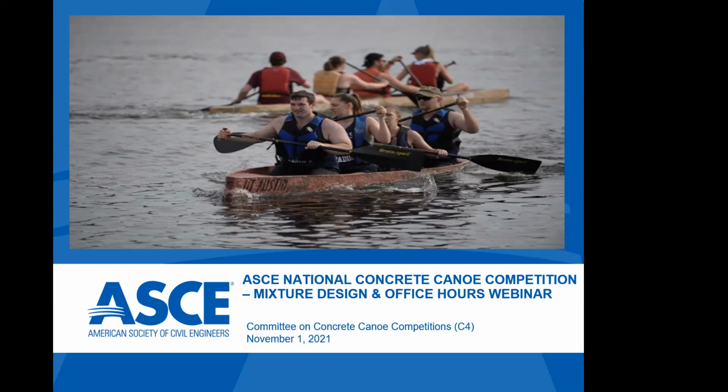Silk fibers inside the concrete, I assume as secondary reinforcement. I would say that is more likely allowed under C 1116. If you have a particular fiber that you want to use, we would suggest that you submit that to the C4, so we can take a look at it. As long as it meets the requirements, or in our opinion does, we can accept it. Let's see. Can we use latex in the mix? If I'm correct, latex is not allowed. Yeah, that's right. So the answer to that is no.